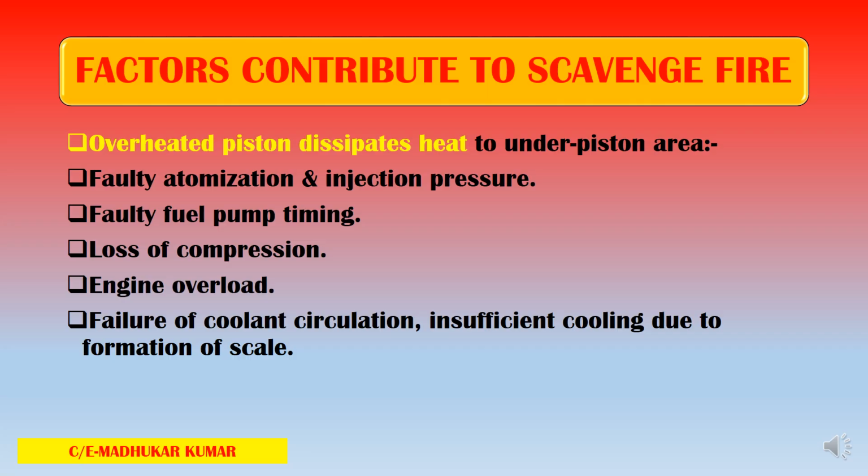Factors which contribute to the scavenge fire, again. Here we are going to see how an overheated piston dissipating heat to the under-piston area contributes towards a scavenge fire. Faulty atomization and injection pressure is going to cause afterburning. When you have afterburning, overheating is quite possible and proper combustion is not there, so this is going to dissipate the heat. Faulty fuel pump timing, again related to the timing of the injection, is going to cause the same thing.